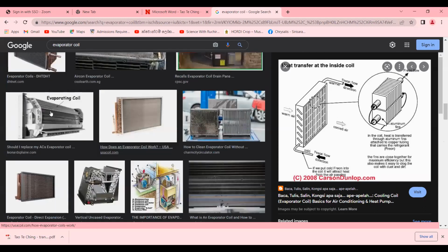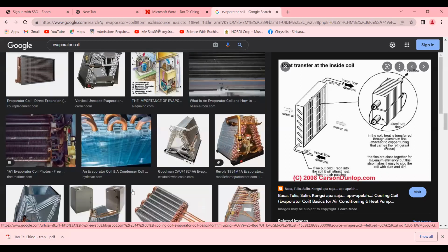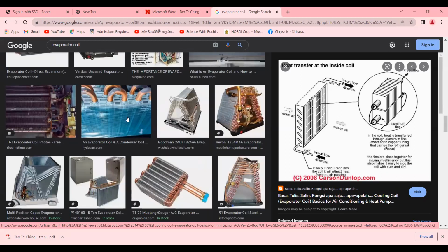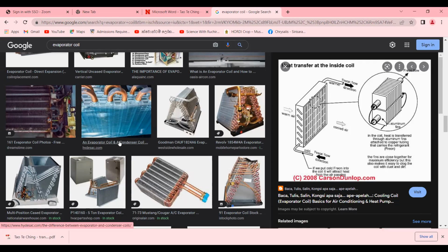This is an evaporator coil in an air conditioner, which you may see inside on the wall. This is the compact construction: the ends are joined with U-like clips. All the U clips insert into the fins, expand, and then at the other end you add the U clips.